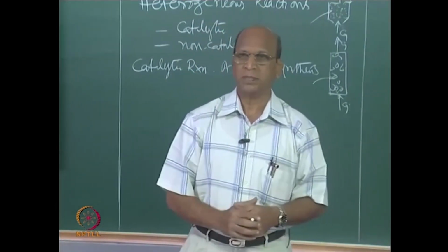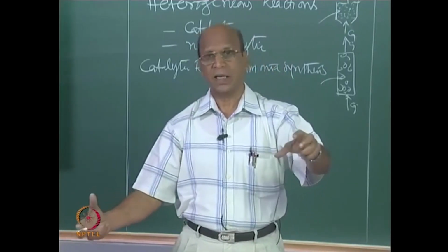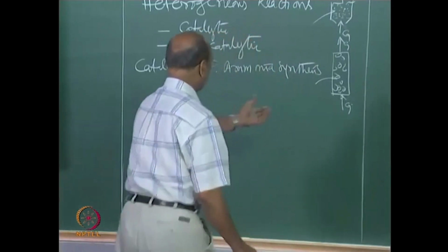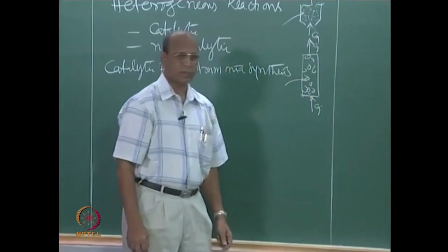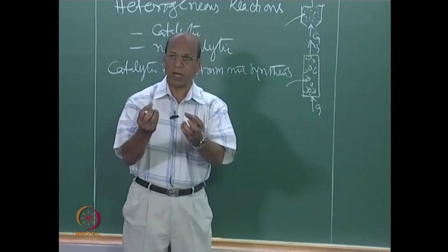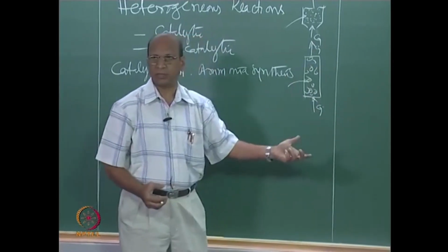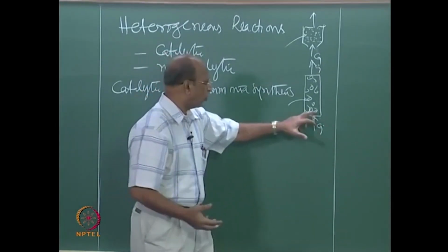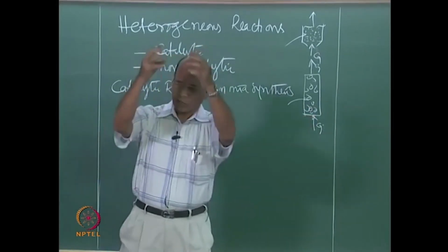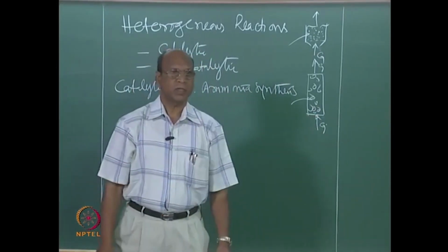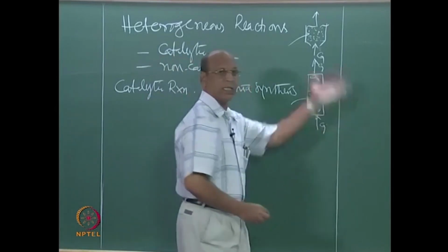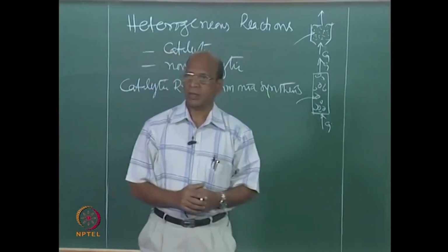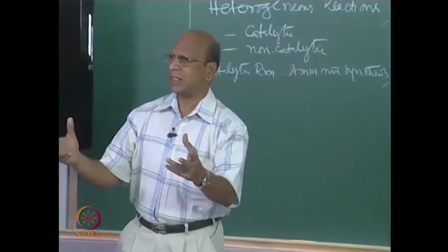Packed bed is the simplest. This also can be used. There is another reactor also called a moving bed reactor. You take the packed bed and put a hole here, not a distributor. A distributor has small holes where the particles cannot fall, only air can enter, or nitrogen and hydrogen can enter. So, now you can put big holes there where the solids can slowly come down. Then you are also sending the gas in the opposite direction. Now, the entire bed is moving, that is why it is called a moving bed. Okay, understood, no? These are not generally difficult.